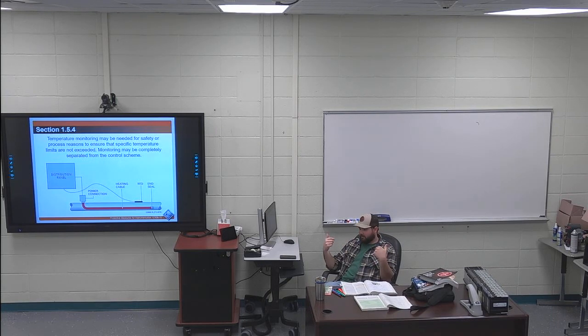We run at 60 hertz for our power, but at a different frequency they could send a different signal, so you wouldn't have to have a separate connection for your TV. I don't know where that technology went, but they're using it for this. They're saying they can send temperature readings at a different frequency on the power line, so you don't have to run a separate communications wire. Pretty cool technology.